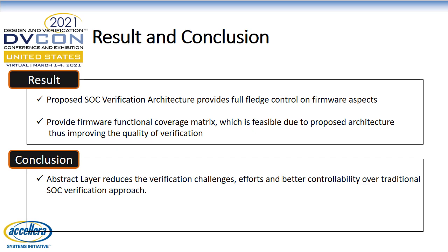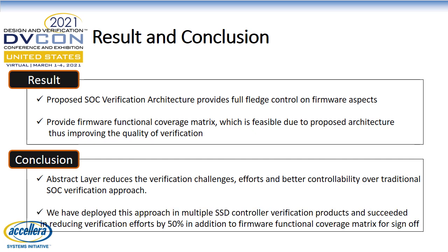In conclusion, the abstract layer reduces verification challenges and efforts, and provides better controllability over traditional SOC verification approaches. We have currently deployed this approach in multiple SSD controller verification products and succeeded in reducing effort by 50%, in addition to the firmware functional coverage metric for sign-off.